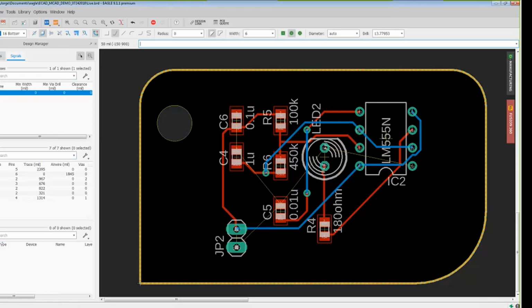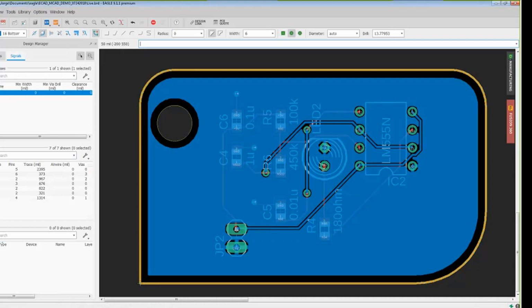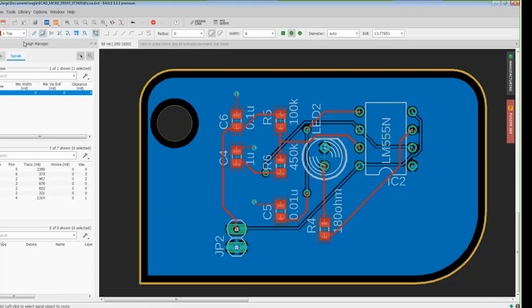That's a brand new feature on this version of Eagle that allows you to take enclosed shapes and polygonize them. And you can put them to any layer as well. Just kind of taking advantage. Okay, cool. Ratsnest. Everything is connected. You'll notice that the rendering order changes depending on what layer has preference. So right now bottom has preference, so it goes on top of everybody else. If I switch to top, then it looks more like what we're used to. So if you're running into that, just double check your preferred layer.